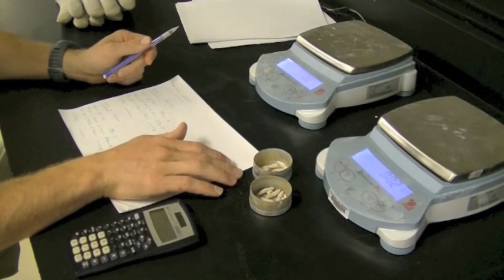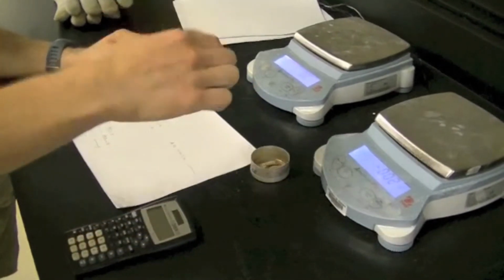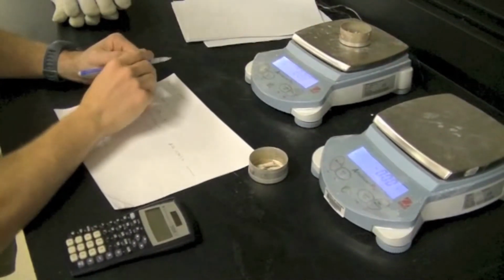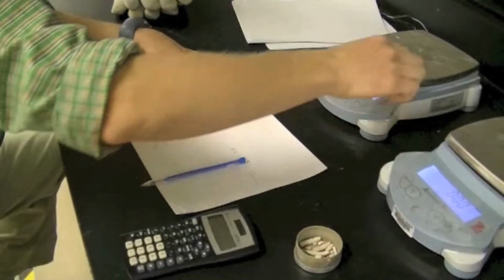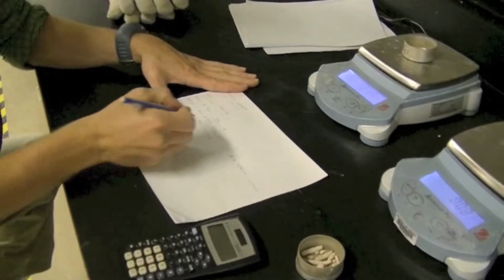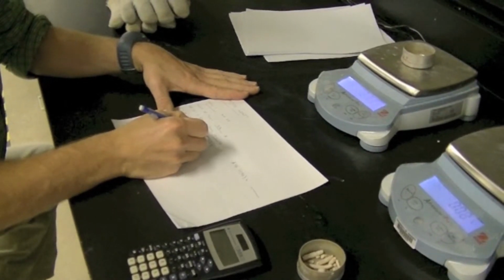Oven dry samples. Once the samples have dried, weigh and record the tare plus the dry soil. Average the 2 moisture contents for the plastic limit portion of the test. Obtain 3 separate moisture contents for the liquid limit trials. There should be 3 of them.